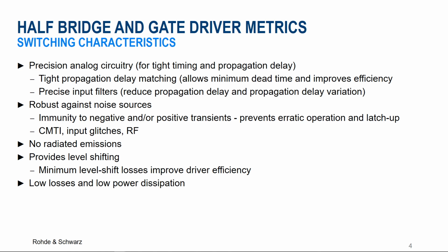Additionally, it's important to characterize and understand the effects of parasitic elements and their impacts on performance, specifically device turn-on and turn-off penalties, slower performance, increased ringing noise, and EMI. It's important to characterize overshoot versus EMI performance versus losses. Level shifting is also required to raise the low current voltage PWM signals from the controller to high current voltage PWM signals to activate IGBTs.